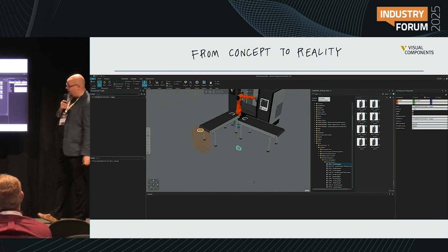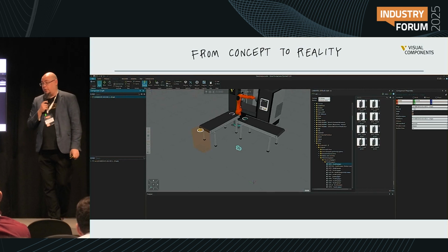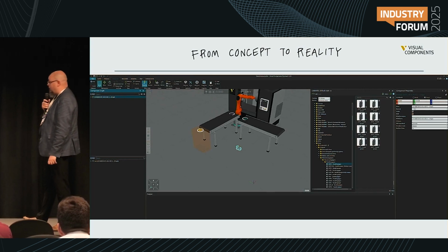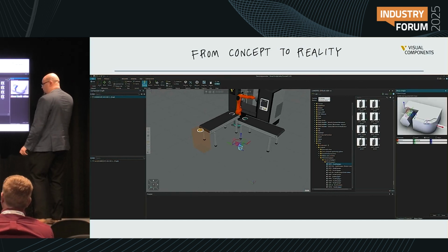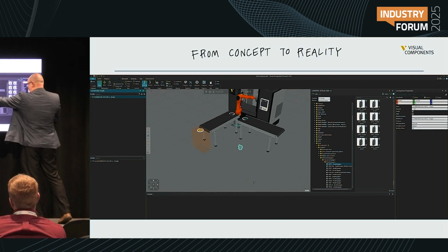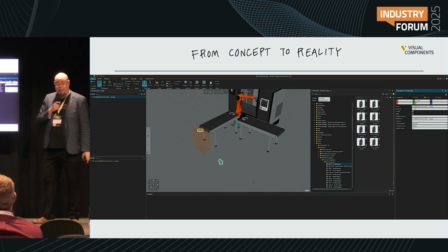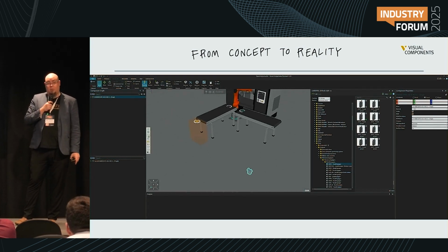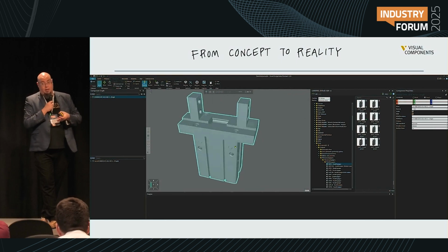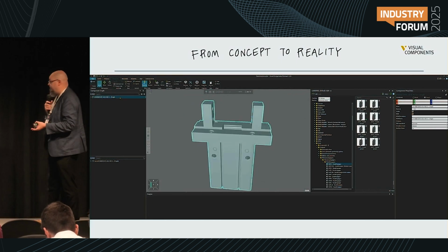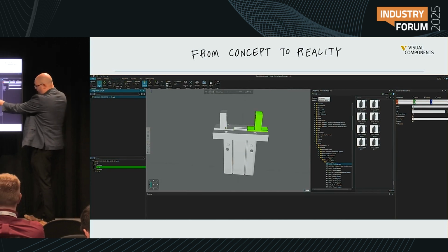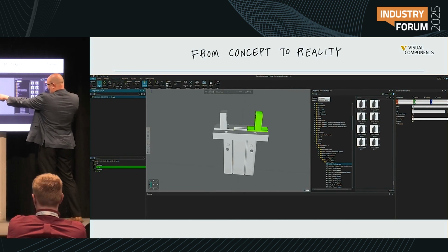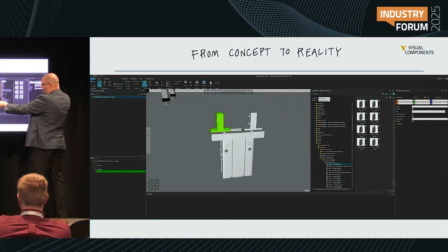You cannot connect it yet into the robot, but we have developed a lot of different tools for how to do it borderline automatically. So first thing is that you need to define its origin. So practically, in this case, a mount plate for the robot, where you are connecting the gripper to the robot. Then, because the hierarchical structure is there, but not the joint information yet,